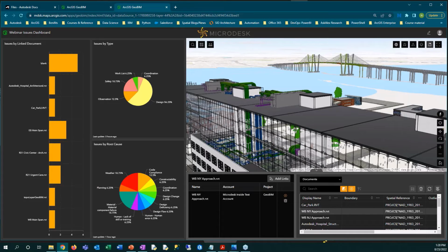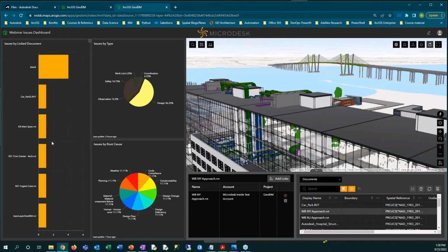The dashboard component is totally configurable. You'll actually have a separate ArcGIS dashboards file created when you create an issues dashboard. And you can go into that within your organization, and you can make edits to the symbology, add or delete portlets, as well as changing attributes that are being displayed within a given portlet. To display their dynamic nature, when I click on a selection here, it's going to update the other portlets to show me a view of what's represented in that segment of the pie slice that I've selected.